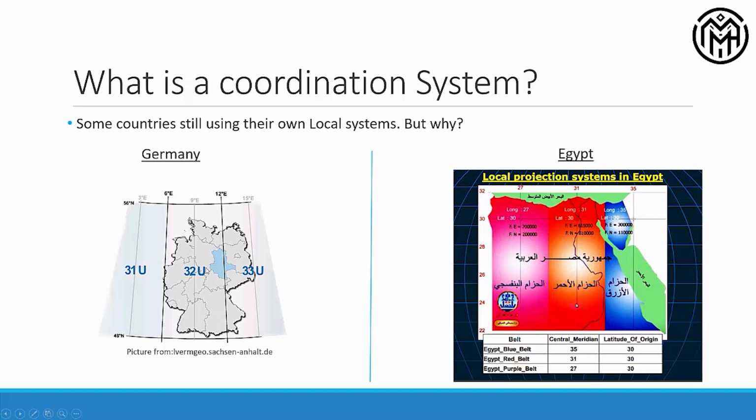For those cities, you will be using the UTM coordinate system according to zone 32U, which means, where will your origin be? I want you to pause the video and decide on paper where the origin point of this coordinate system is. And we agreed that we are not talking about 0 and 0, we are talking about 500 kilometers and 0. Find me this point and continue the video again.